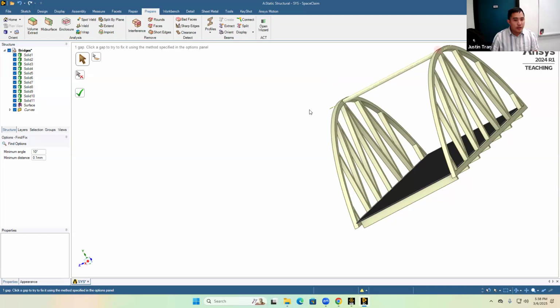Okay, so to start converting a geometry into shells, you're going to click on the Prepare tab at the top of the screen. This Prepare tab has a lot of different tools that you can use to modify and alter the geometry. In particular, we're going to be using a tool here called the mid-surface operation, which is what we talked about. It's grayed out for now just because I'm away from the window, but one second. Okay. All right, so go ahead and click on mid-surface.